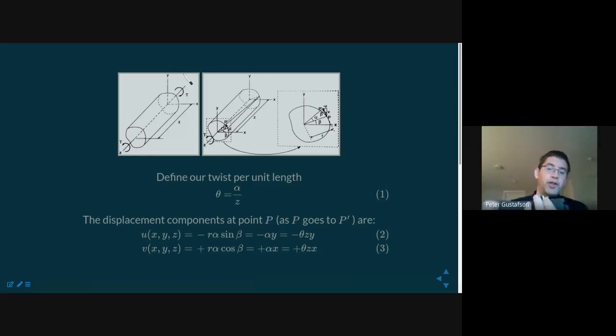So what you see here is when it comes down to a shear problem, we see a large angular change, and that angular change is most dramatic in this cross section, because two points that were otherwise adjacent to each other but are not bonded to each other slide past each other. Now, if they are bonded to each other, if it's a circular cross-section, the mathematics will mean that they don't warp in that direction. But if it's a non-circular cross-section, if I squish this thing to be an ellipse first, and I glued it together, and then I twisted it, you would see warping in an ellipse.